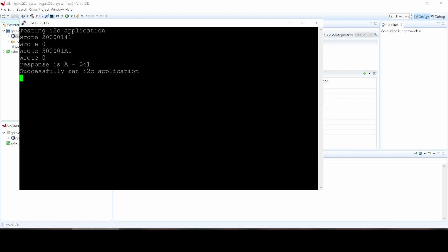Like I said last time, we went through the spec of the I2C EEPROM, and we talked about the start condition, sending the command bit, then sending the high address, the low address, and then either sending data or getting a response. Then we talked about the stop bit scenario, and I went through the waveform. So I'm not going to go over that too much anymore.